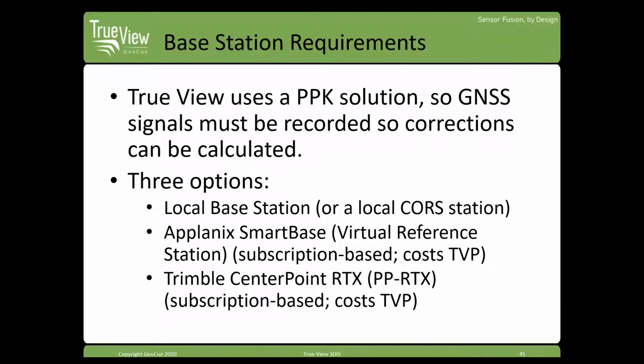So you can use Applanix SMARTBase. What it does is it creates a RINEX data set for your location by using multiple stations around your area. This does allow for a longer baseline, so further distance away from your flight area, because it is using multiple stations.